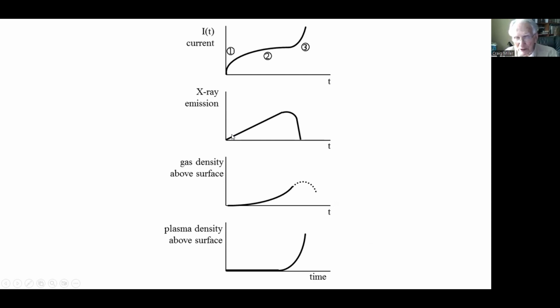Anytime you have voltage applied across a gap in vacuum, you can have X-rays. Of course, for a couple thousand volts, they're very weak. But even for underground vacuum interrupters, which are rated at 24 to 32,000 volts AC, they have to withstand lightning strikes of 100,000 volts or more. And when such devices are built and tested, a significant amount of X-rays are emitted, and you have to worry about shielding for any personnel.